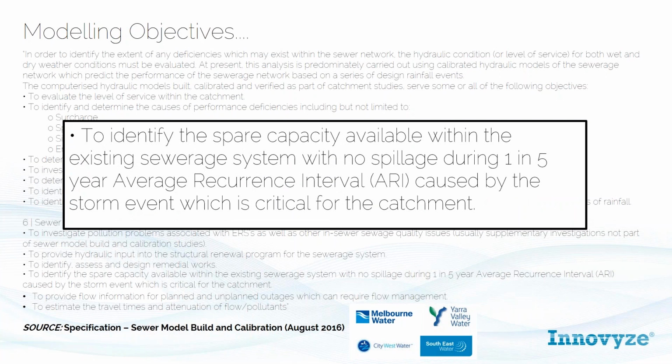So Matt, did you want to speak to the difference maybe between how they design in Victoria versus regionally in Southeast Queensland? Probably the first comment I'd like to make is that Australia doesn't have combined sewer stormwater systems. We do have separate systems. That being said, we do have older networks that suffer from inflow infiltration. So when we analyse our sewer networks, wet weather flows, performance in wet weather conditions, we still do refer to storm events. So I guess in Melbourne, they do refer to a 5-year average recurrence interval, or ARI, event and containment of that event.